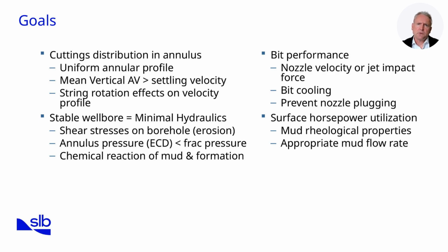Next, a stable wellbore with minimal hydraulics. Excessive annular velocity can erode the borehole, while high ECD can exceed the fracture gradient. In depleted sandstone formations, this often leads to severe lost circulation. By applying only the necessary hydraulics, we keep the wellbore intact and minimize instability.